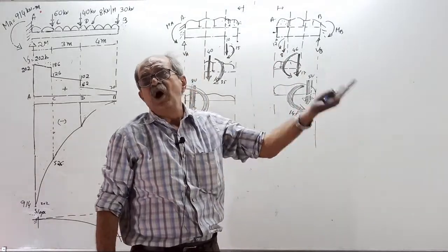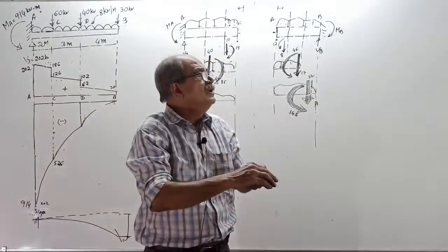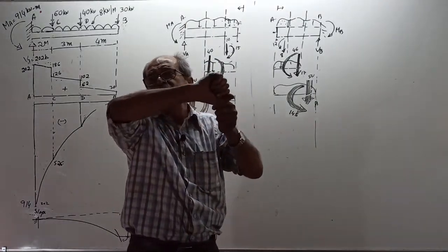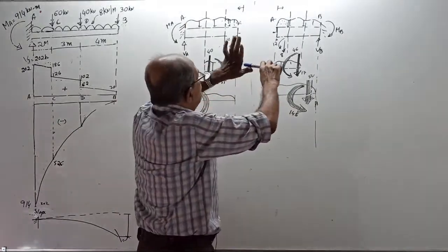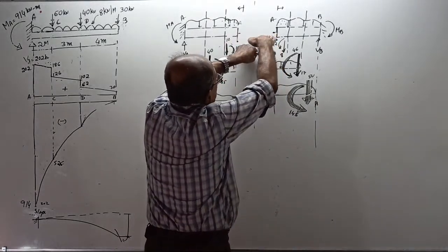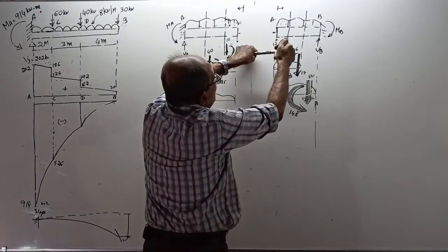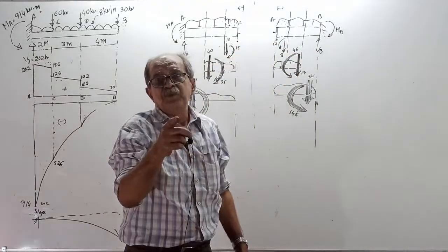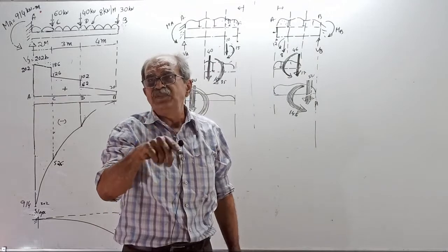Load will keep on increasing under normal loading. Moment of the load also will keep on increasing. Therefore, if you have a cantilever here, if you apply some spread loading from free end to fixed end, as you move, shear force and bending moment both keep on increasing.